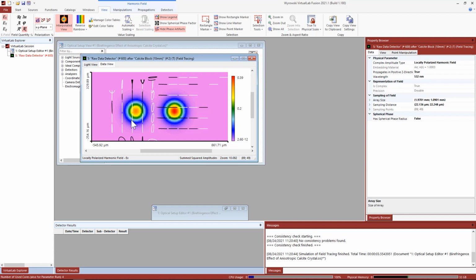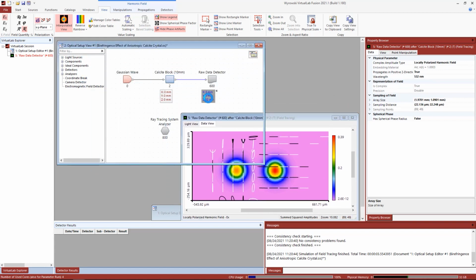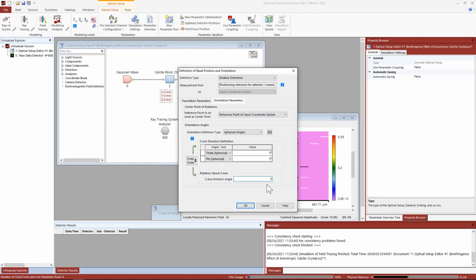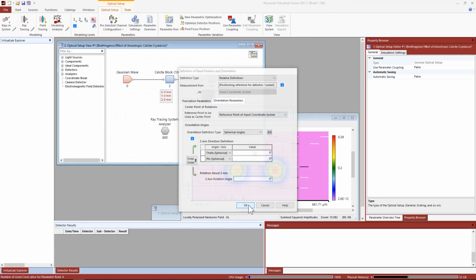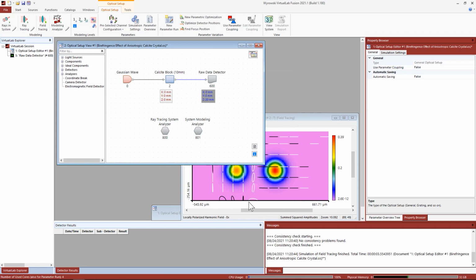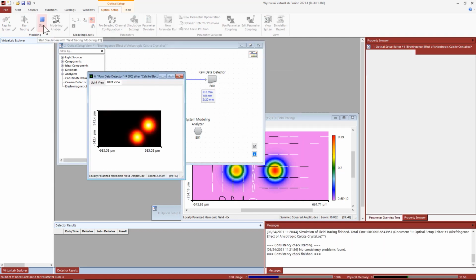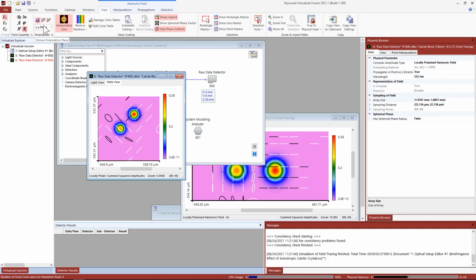Note that we have rotated the detector 45 degrees, and that will influence the definition of a polarization at this plane exclusively. Let me illustrate that by simply removing here this 45-degree angle and setting it to 0. That means we, of course, do not use that rotation, and run the simulation again. We're still going to get the same physical result, but now at 45 degrees.